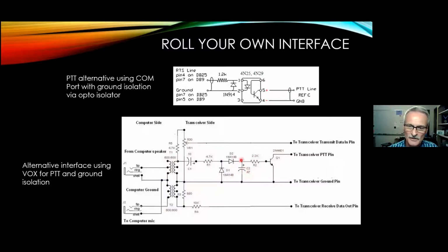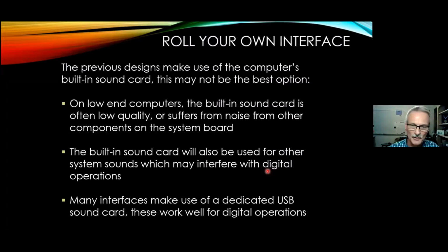But a circuit like this can certainly be made to work, and then you don't have to have a serial port on your computer to assert the push-to-talk function. There's other ways we'll talk about in a minute. So the design I just showed you is making use of the sound card that's built into the computer.